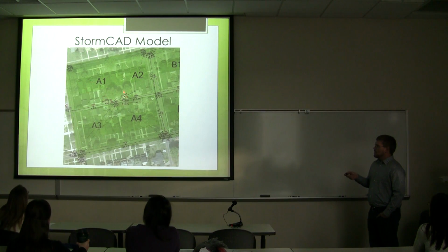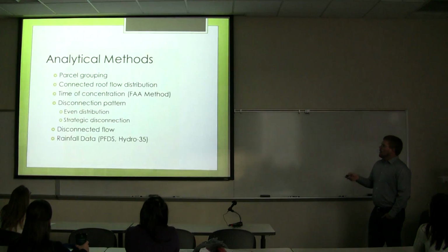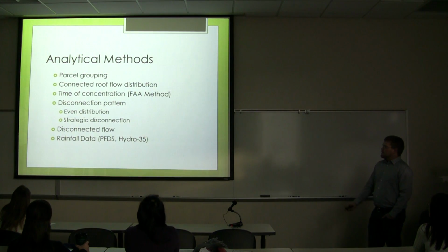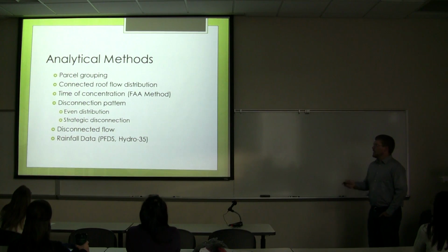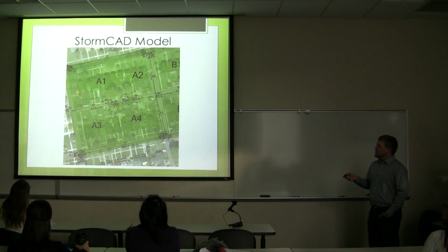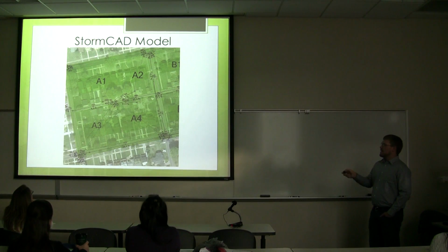So this section all was at one slope direction, and it would eventually feed into this catch basin along with these here in similar patterns throughout. And then our connected roof flow distribution, as Andrew talked about, is those respective catchments for the surface flow made their own catchments for the connected housing, and they would flow together into one pipe that fed into the same transition of the combined sewer system.